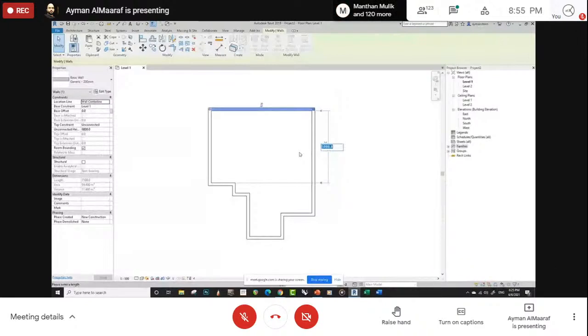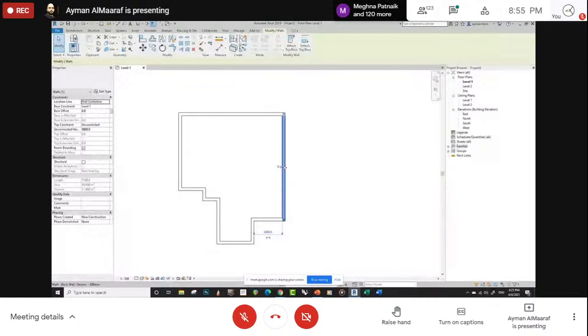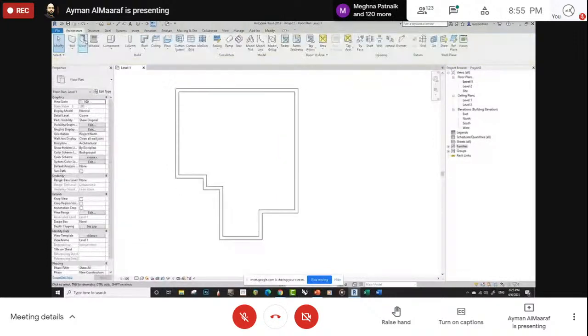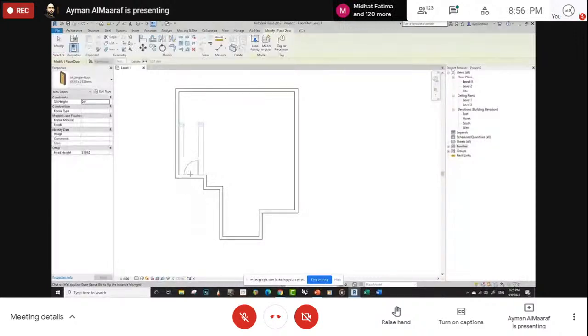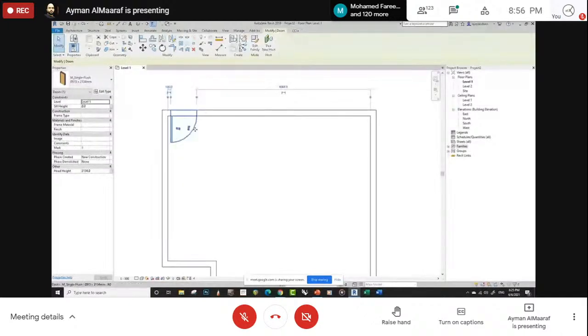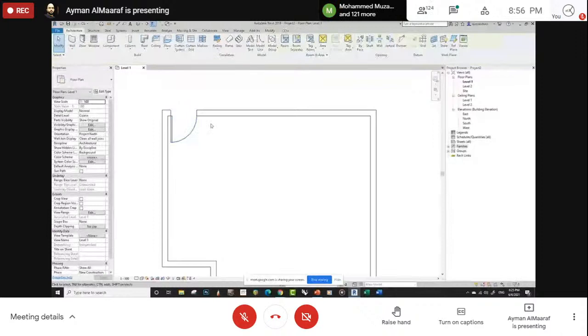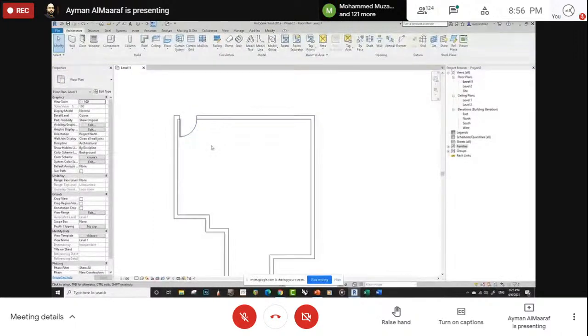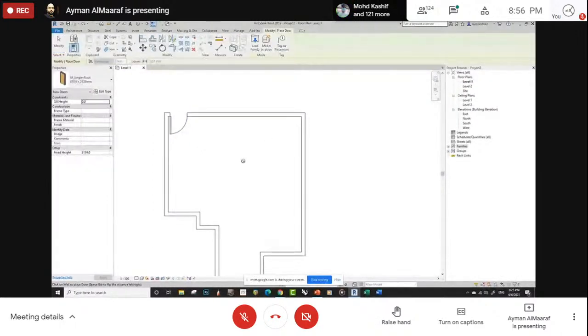So we have also a tool that's called door. It's a category and also a tool to draw doors. You can just highlight in the model and click, and it will open the door. And it needs a wall to be hosted on. So if we created another door, you can't create it in the white canvas or anywhere, but you need a wall.